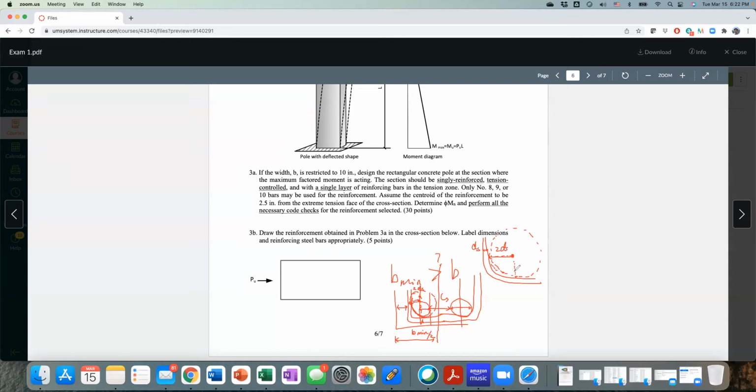Now, when you have that, remember you still need to put your bars there, right? You need to tie your bar to the stirrups. You need to secure that bar in the corner, or else the bar is going to roll around, isn't it? So to make sure it lays horizontally, the bar will sit like this.